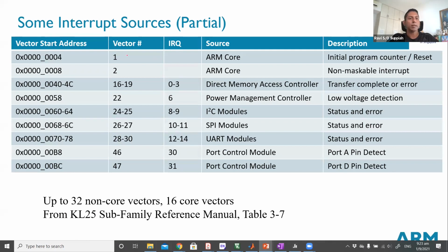At each address I store 4 bytes of information, and that 4 bytes is actually the address of where the interrupt handler is located in memory.